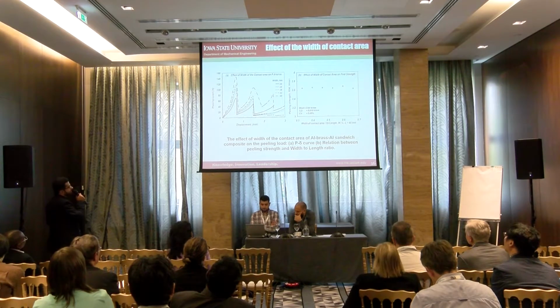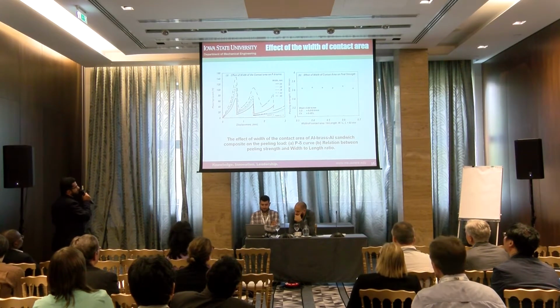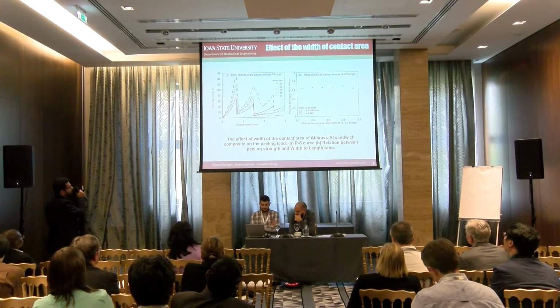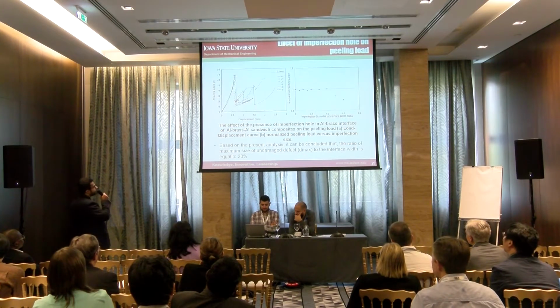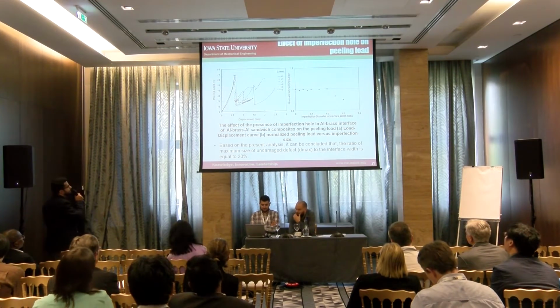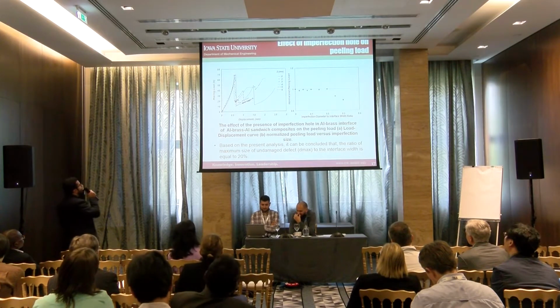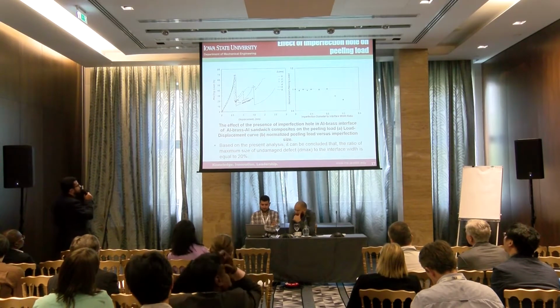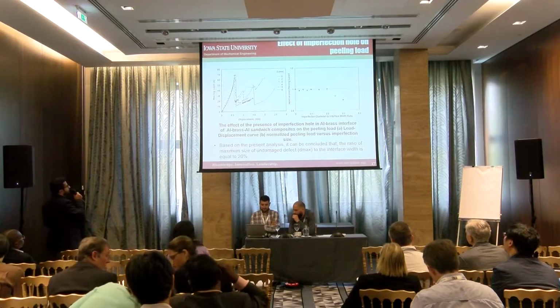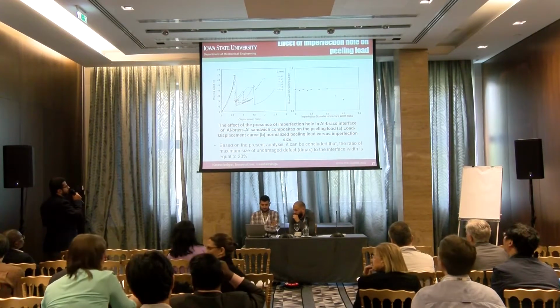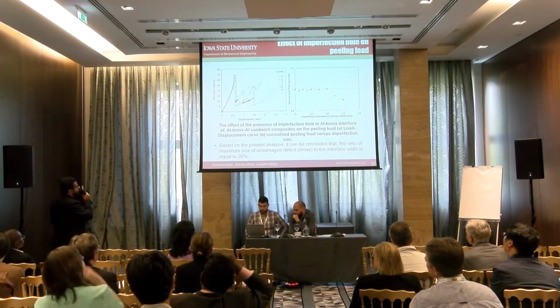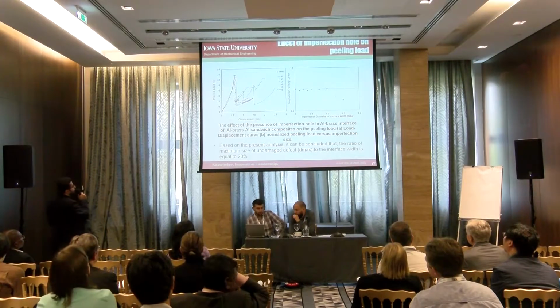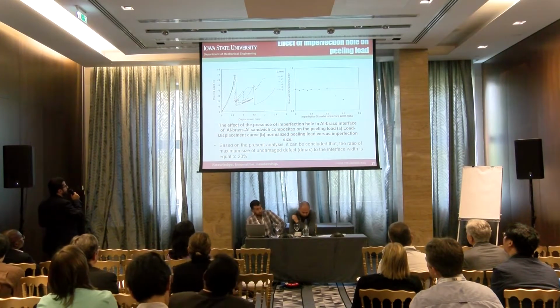It's a very good parameter, so we can predict the peeling strength, how it's affected in a linear way for all the width samples. Finally, the effect of the temperature and the imperfection hole in the peeling load. We used sizes starting from 0, where there is no hole, and we started to increase the size of the D. All of them, we can see, have almost the same peeling load.